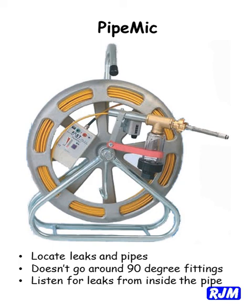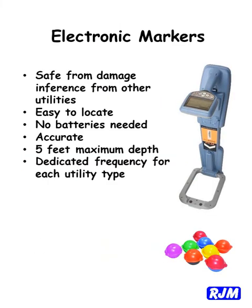Locate with the built-in sonde to find the pipe and the leak. It's limited to pipes without 90-degree bends. If you have electronic markers above your pipe, it's easy to find. Just flip down the antenna and search for the strongest signal.